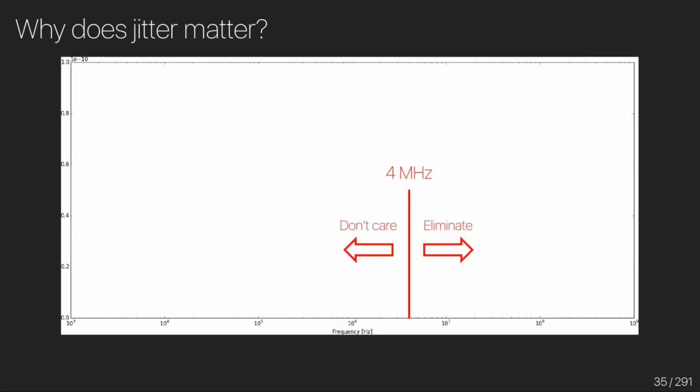However, there's another aspect where jitter can cause problems. Jitter can also have a frequency. This instability, the shifting to the left and to the right, can be very slow or it can be very quick. And so we have high frequency jitter and low frequency jitter. So the HDMI standard says that jitter below 4 megahertz is called low frequency, and above 4 megahertz is high frequency. Each device and circuit that you have in your system adds a little bit of low frequency and a little bit of high frequency jitter. The problem is that the HDMI standard only cares about high frequency jitter. So HDMI was created for home applications where you have one direct connection from source to sink. You may add another device in between, but it's fairly simple. But when you send the signal through multiple different devices, low frequency jitter can accumulate.